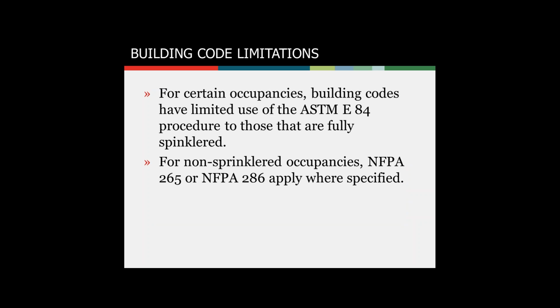In addition to the ASTM E84, there are other tests specified by NFPA 265 or NFPA 286. These are, again, interior finish tests, but the specimen, instead of being held in a horizontal configuration, is held in a vertical configuration.